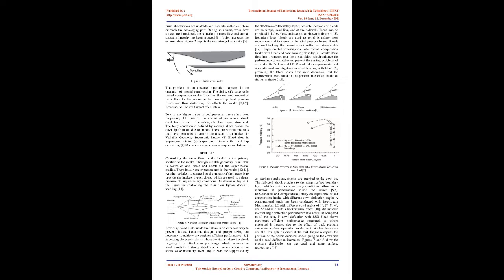This phenomenon will influence the flow field's mass flow rate and characteristics inside the intake and could also affect the stability of the engine. Generally, unstart of the intake is observed through the expulsion of the shock system and massive spillage, leading to degraded pressure recovery and large flow distortion at the exit.